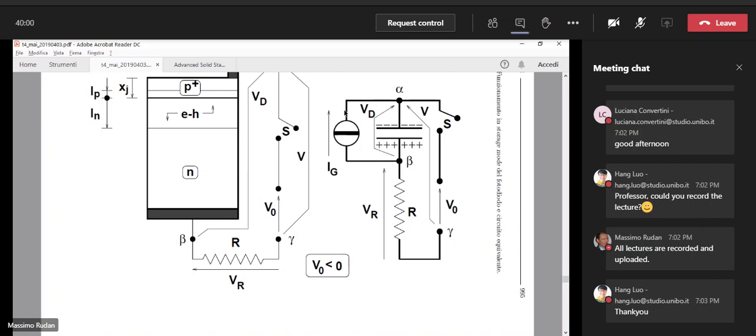So beta was originally equal to 0, the potential in beta, because there was no current flowing through the resistance R. So at the time when we close the switch, the voltage at beta is 0. Then it becomes negative. Okay. Due to that, we have a peak of current through the resistance, because the resistance, 1 instant before closing the switch, has 0 voltage across it. 1 instant after has a negative voltage across it. So we have a large current flowing through the resistance. And this current produces a voltage drop, VR, that is of course negative, through the resistance. Okay?